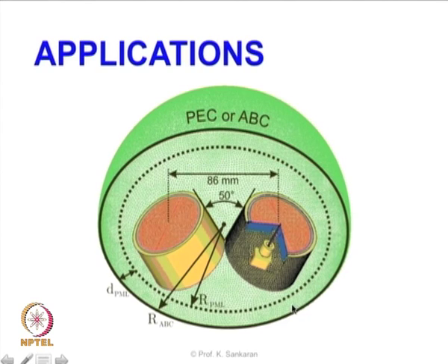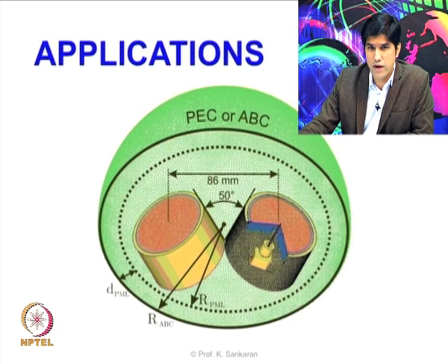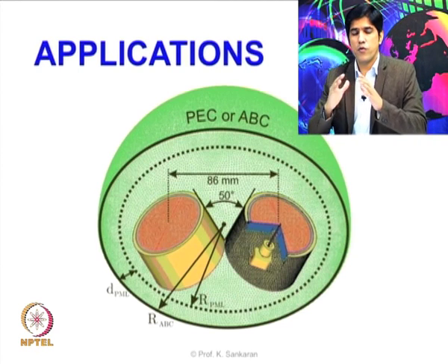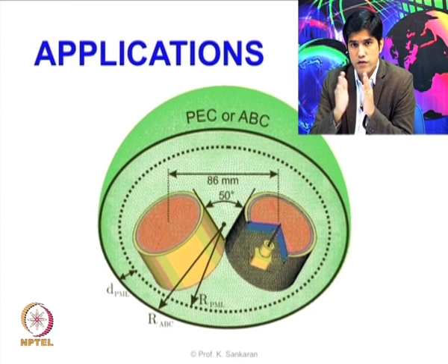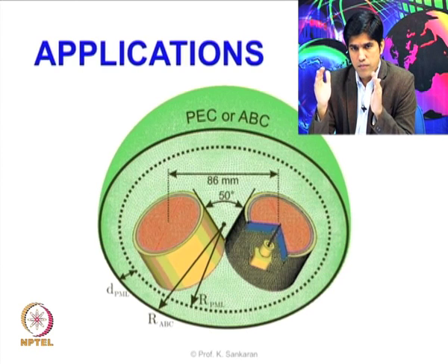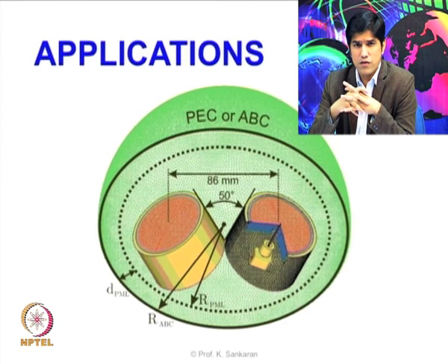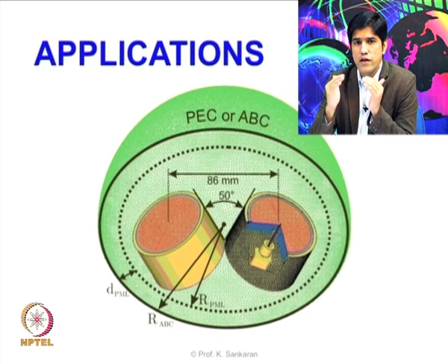Before having the radial PML or spherical PML, what we might do is keep the direction radial, but keep the boundary condition quite far away. It means that you are doing too much computation, too many cells in between, and these cells are kept only because you want to reduce the reflection. There is no other reason why you have to have so many cells. If you keep the boundary condition closer you get so much reflection, and this is quite a difficult problem to compute because you are interested in coupling which is very low in terms of the decibel value. So any source of reflection coming from the boundary should be avoided to the minimum.